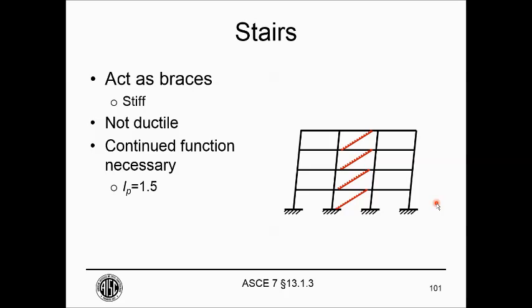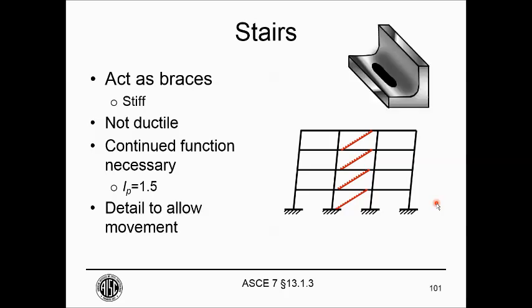ASCE 7 tells us to design them for extra force, but we also need to detail them to allow the lateral drift to develop without damaging the stair system. So details with slotted holes are often used. We want to make sure that those slotted holes don't bind up and don't compromise the ability of the connections to resist gravity forces.